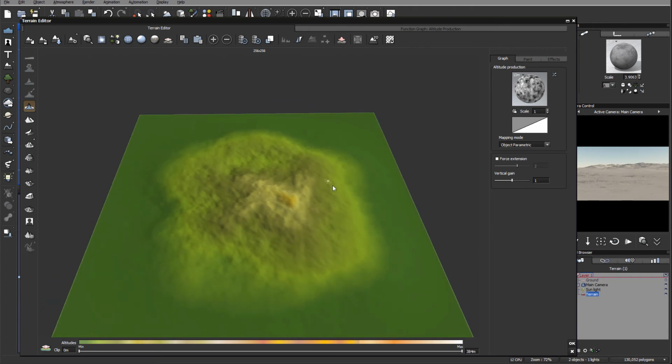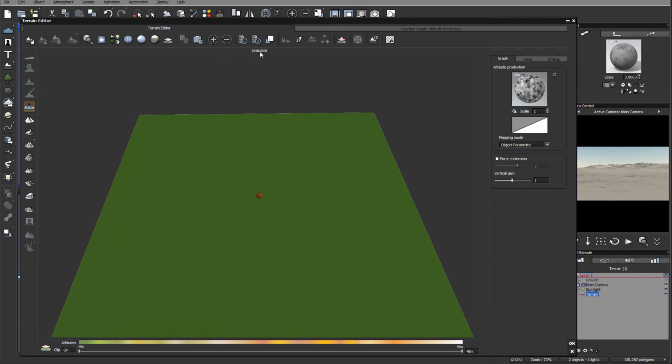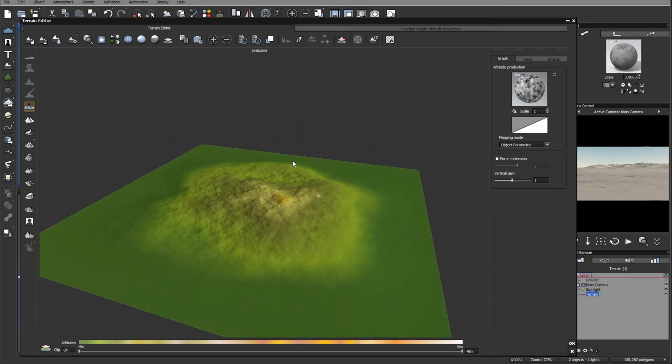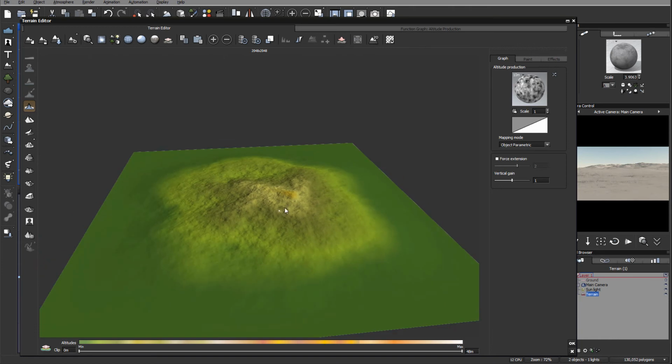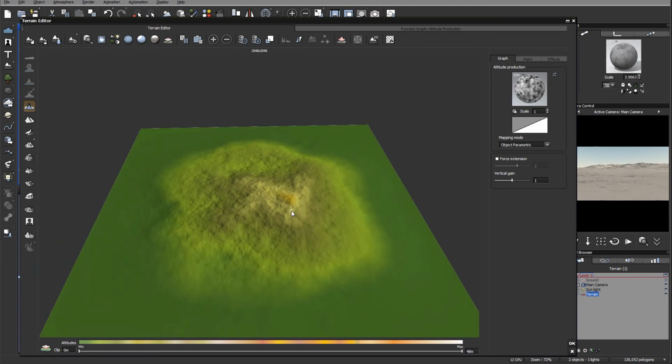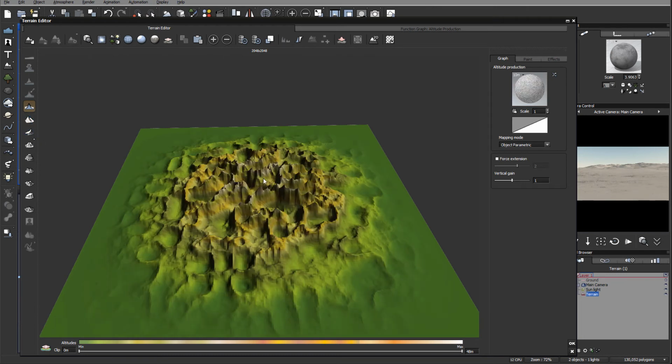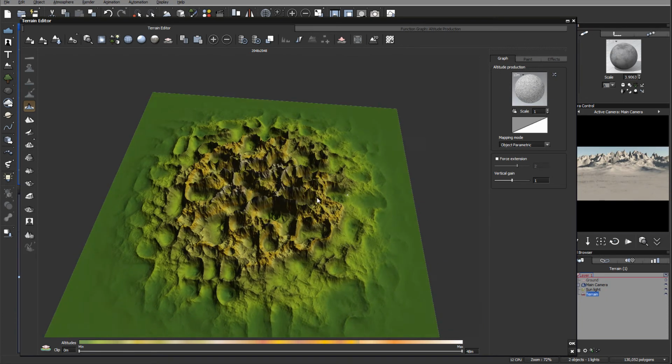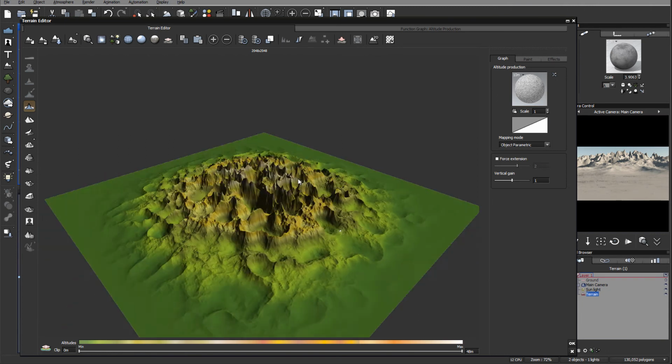Right here, what I want to do is create some sci-fi terrain, and we'll do this by increasing the resolution of our terrain. I actually want to create 2048. You can create a little bit higher. The reason is you can see how much grain we have, a lot more details, and that's what I'm looking for. After this, we'll select and click peaks. Notice when we apply the peaks, it changes our structure of altitude production as well. We have it now very nice, very interesting.